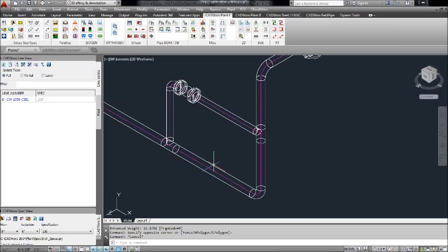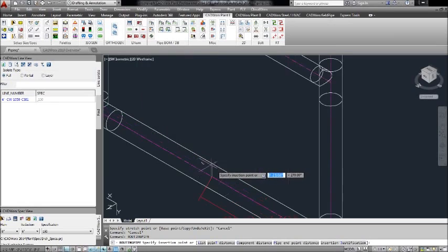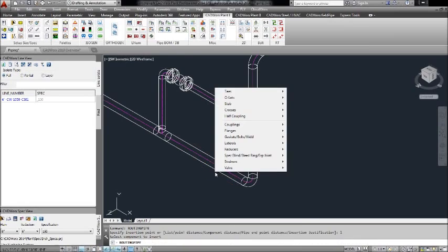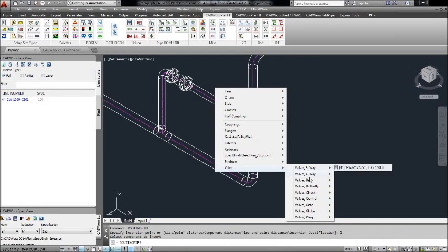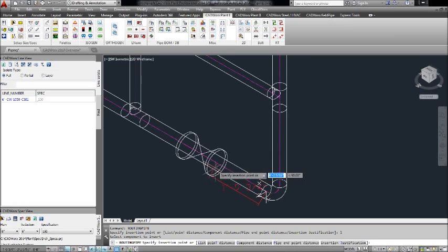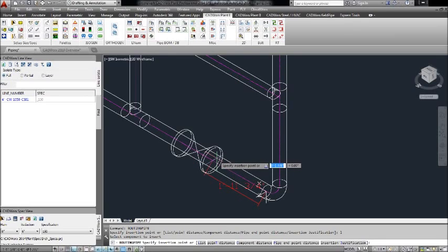Okay, another example here, we'll finish out this control loop. I'll add this control valve, and by activating the plus grip, I'm going to get another T there, but I'm going to list out and get my whole spec out here, and I'm going to go get the control valve flange. My goal here is to set this valve right on the center point of this internal spool piece on our control loop.